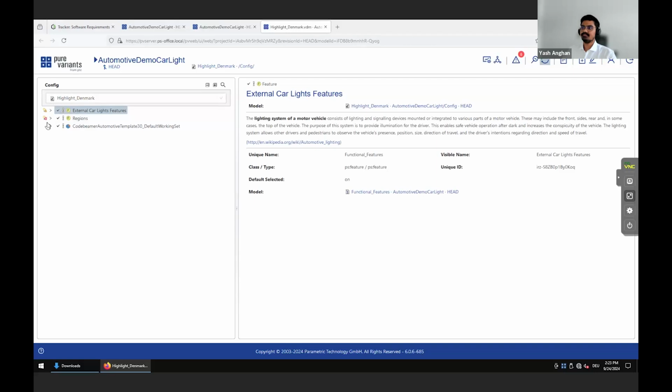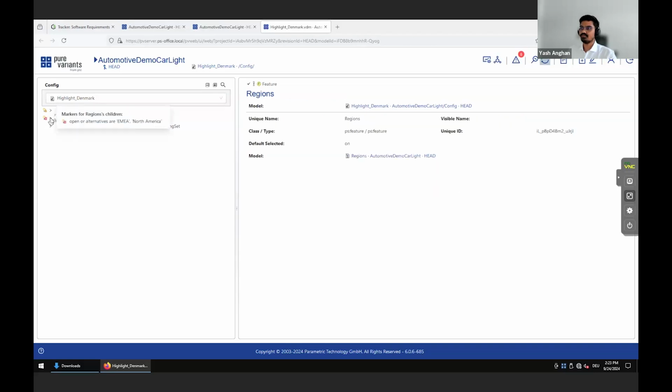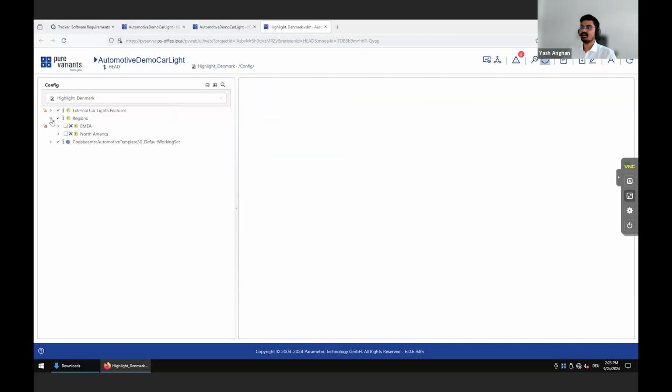You see there are some errors, which are shown by pure::variants directly on the left hand side, and you see why these errors are happening: because those are the OR feature types. Even here, in the beam configuration, I have some selection locked. Why? Because I inherited this model from highlight, and in the highlight variant model I already selected these features, so these features are no longer available for selection.